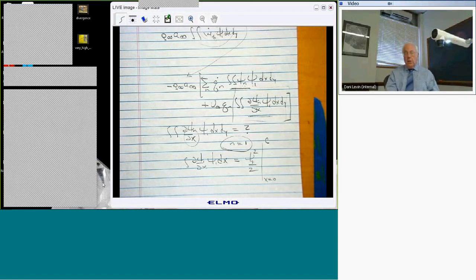On the other hand, the n equals 2 mode is critical, because that gives you a non-zero result. While it's true that the modes themselves are orthogonal, the derivative of one mode is not orthogonal to the function of a different mode. So it's the so-called off-diagonal terms from this contribution that often generate the flutter mechanism, not only for panel flutter, but also for wing flutter.